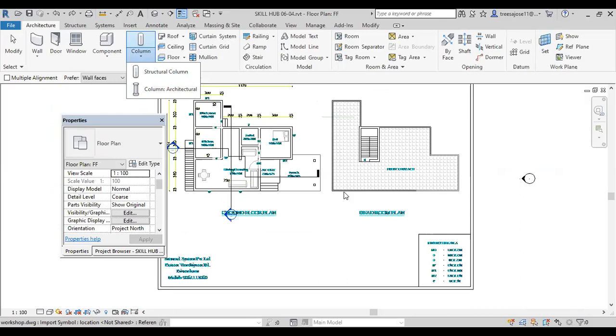Normally, while doing models in Revit, the procedure is this. In the AutoCAD plan we have, simply speaking, a 2-story building, with a ground floor plan and a first floor plan. You import that into the ground floor and finish the ground floor plan. After that, I have to create the first floor.